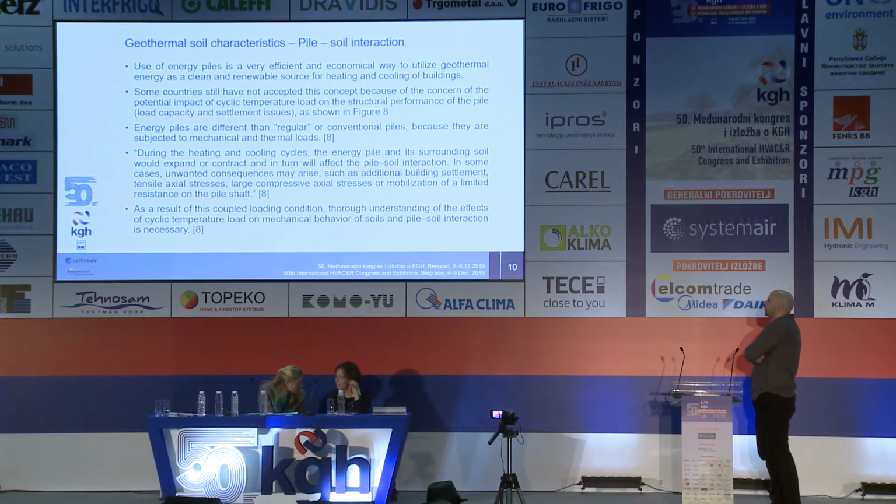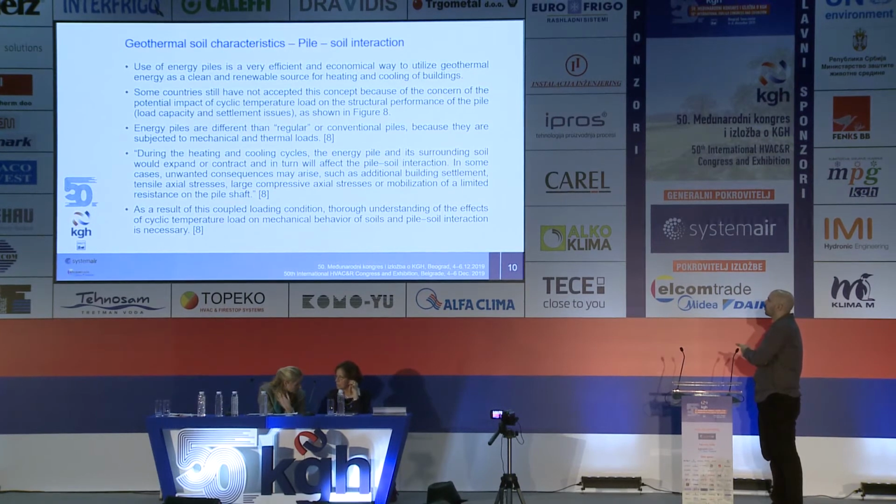Like I already said, because of that, some countries still have not accepted this concept because of the concern of the potential impact of cyclic temperature load on the structural performance of the pile. It can affect its load capacity and settlement issues.